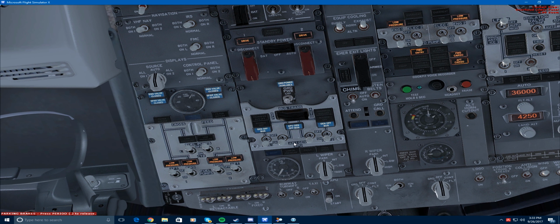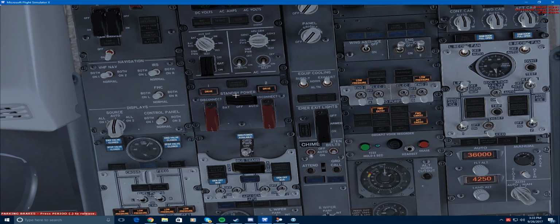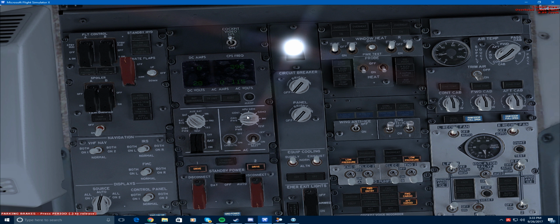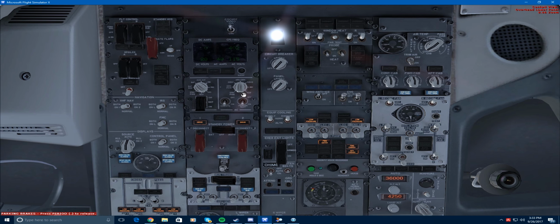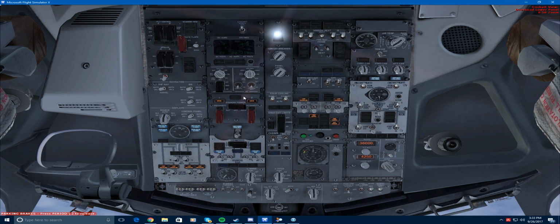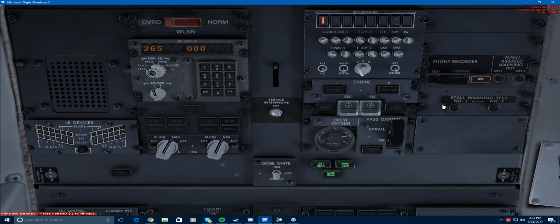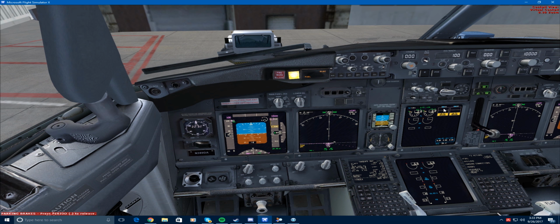I'm going to tell the aircraft to begin using power from the APU gen, and we don't need the GPU power anymore. Now that we have the APU on, I want this display to tell me how much power is coming directly from the APU, so I switch this knob back up to APU gen. We're almost done.